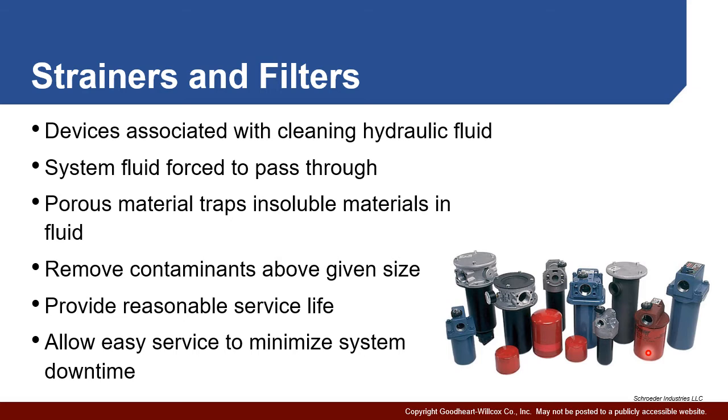And that's something you're going to build into your preventative maintenance schedule. They are designed to be serviced relatively easily. Oftentimes you'll see these covers are designed to just screw right off. You can then replace the filter itself and put it back together and get your system back up and operating in only a few minutes. So there are variations on that, but that's the common mechanism for mounting filters in systems. There are also some other devices you'll see on the top here, which we'll talk a little bit about: indicators, valves, etc., maybe a pressure gauge as well, that are all kind of integral to the system.